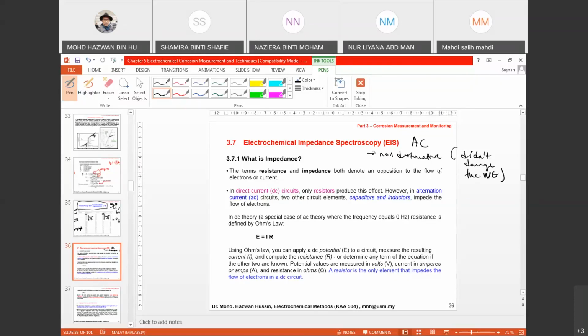So that is why a good practice, when you do a sequence of electrochemical processes at one time, is to do OCP first, followed by EIS, and followed by potentiodynamic polarization, if you want to get all three data from one experiment. With OCP you don't apply current, no current is being applied.